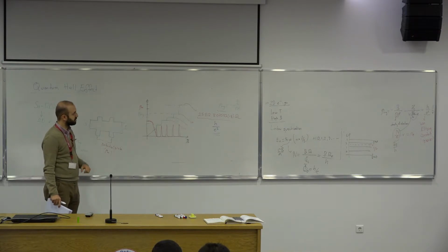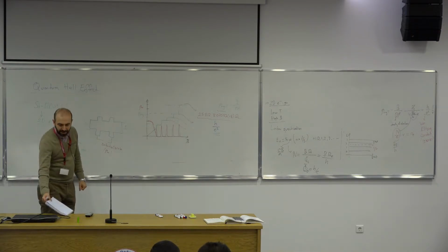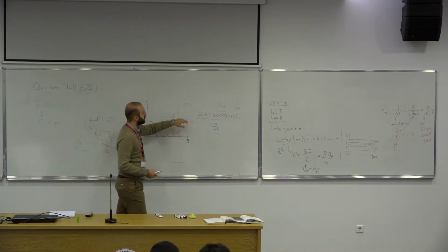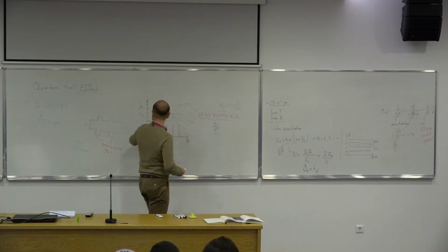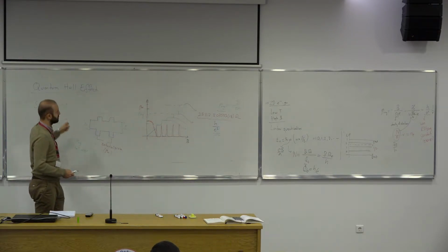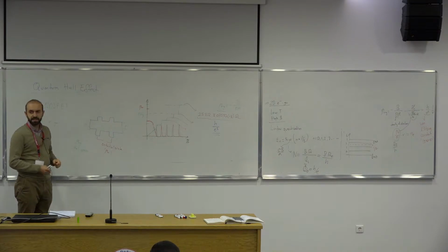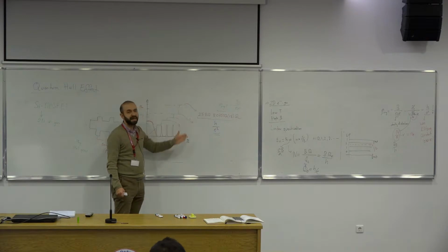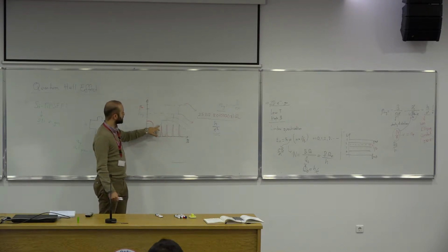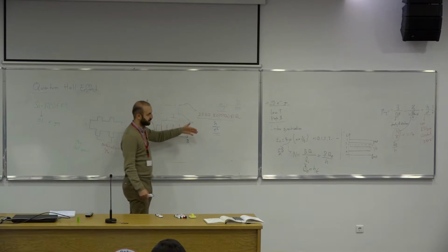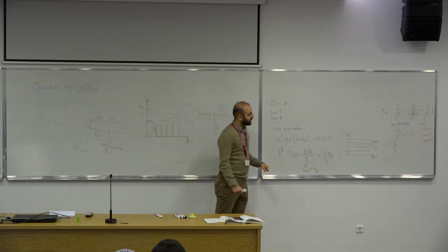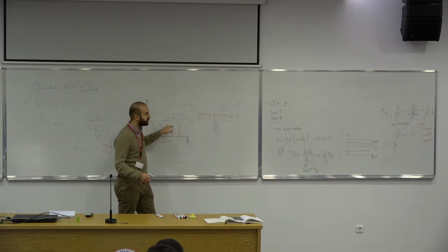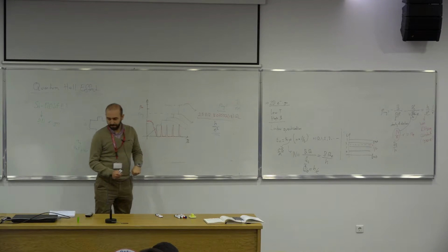So it's very simple to achieve, and this thing is extremely robust for any such system. For silicon MOSFETs, when you form a 2D gas, you don't have to go to these really high magnetic fields. You can work with much lower plateaus, for instance, much higher Landau levels. You'll get 1 over nu of that value, and that value will be the reference of your resistance.